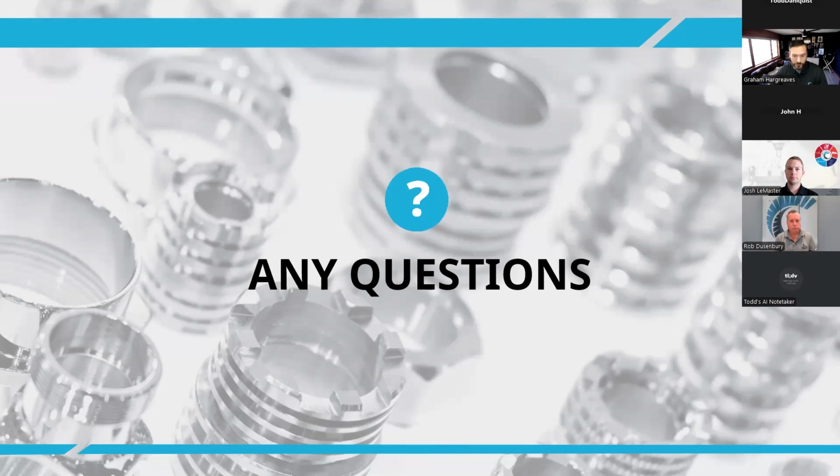To your point about tool assemblies, yeah, you do need to have a tool library that's well defined with tooling assemblies. So a cutter and a holder, Mastercam and CAM Assist, in order to work together, need to be able to see that in your tool set, in your tool library. So yeah, and to that point, I would say your tool library really is one of the most important inputs into CAM Assist to make sure that we have those tool assemblies well defined, but also have the tooling options needed to machine that part complete. So the right tools with the right gauge length and so forth.